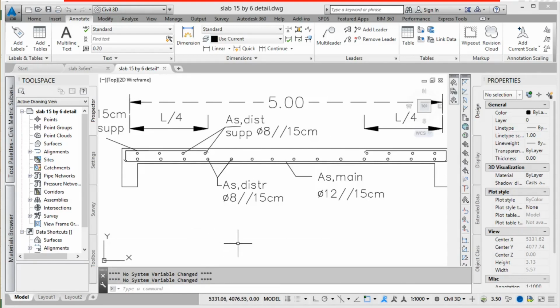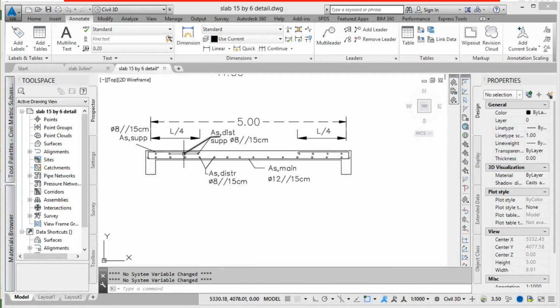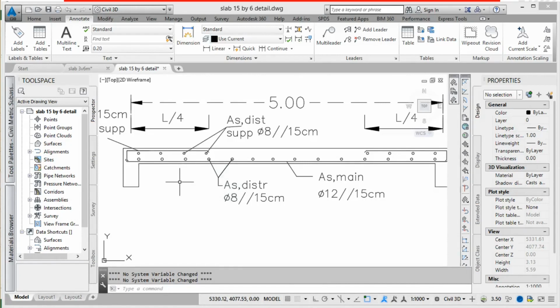So having a minimal reinforcement here on the top too will be advised in those conditions, for example a building with strong wind or some other axial force making the slab have traction here. So this is why some softwares will give this premium calculation with the steel here on the top too.